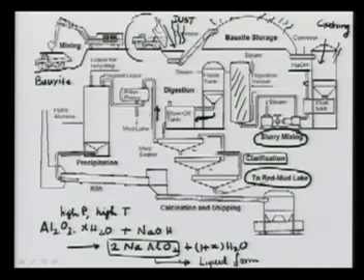After having dissolved the Al2O3 in the form of sodium aluminate, as you see here, what happens to this one? There may still be some impurities. Therefore, what we do is we pass the clearer liquor through the filter press. This is my next step.